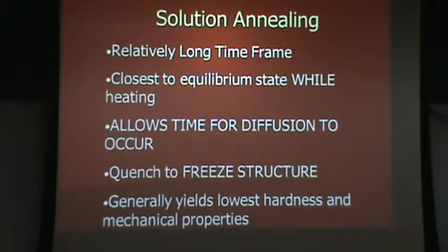So let's talk about that. If I have an austenitic stainless steel, like I say a 304, very common nickel chrome based steel, pretty good corrosion resistance. The chrome that's in there will have a tendency to want to form a chromium carbide with any carbon that might be present. Now, that grade in particular has a fairly low carbon content. We're talking about, say, 0.03, 0.04, so it's pretty low.